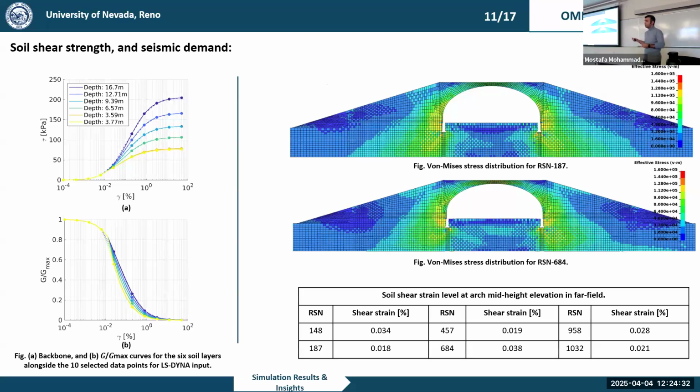I use this criterion because the model I'm using works based on the deviatoric stress tensor, and that deviatoric stress tensor can be converted to the von Mises stress based on some formulation. If we compare our von Mises stress distribution with 2 times our tau max, and it exceeds that amount, it will enter the failure zone. If not, it doesn't.